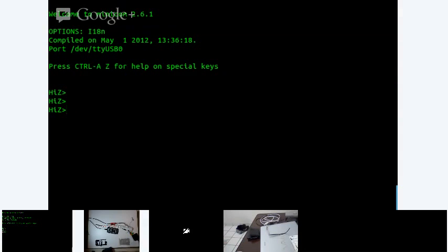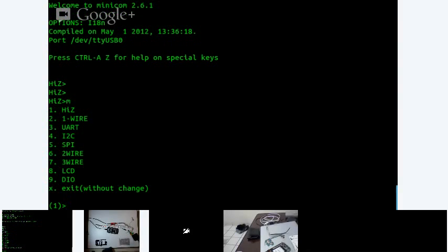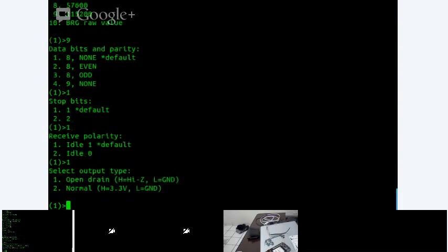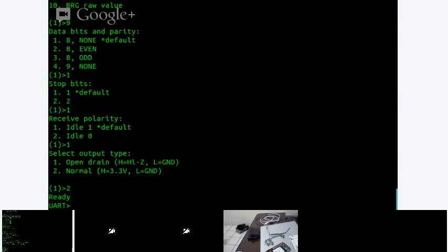It's either USB0 or USB1, and I never know which one's which, because sometimes my ADK initializes before the Bus Pirate does, and I end up trying to connect UART to my ADK, which doesn't really do much. You know that little clock? That's ADK.